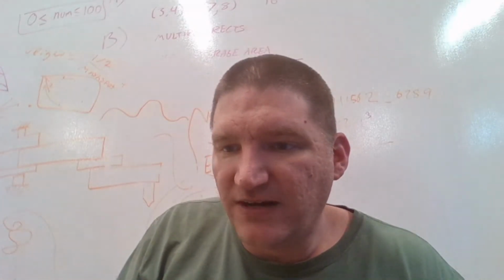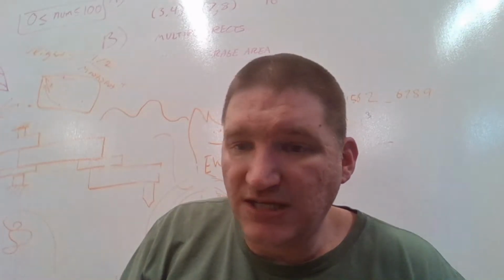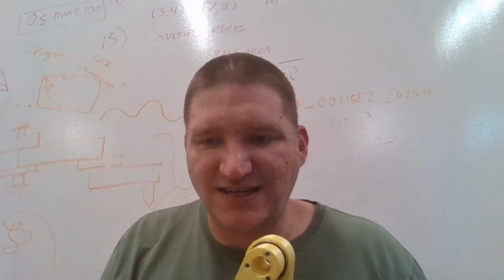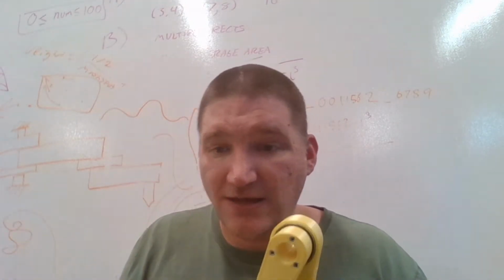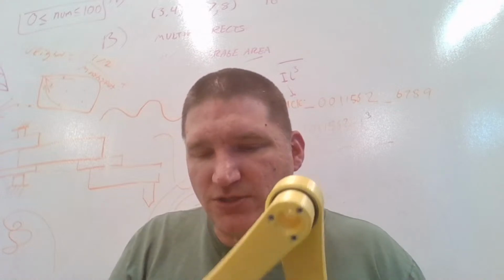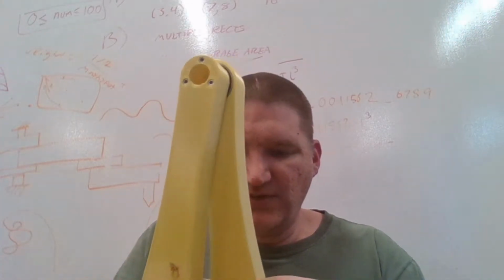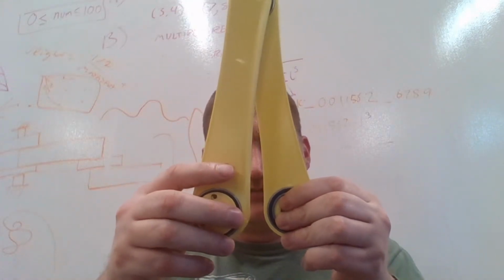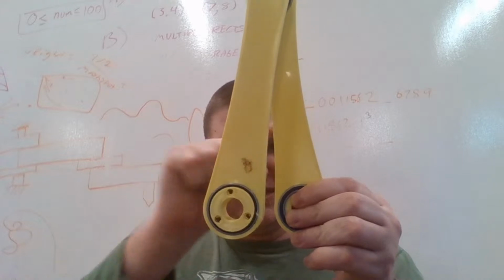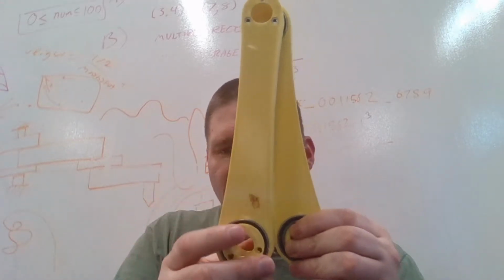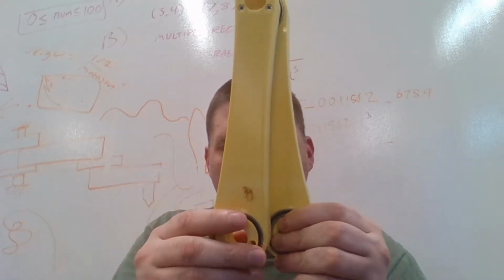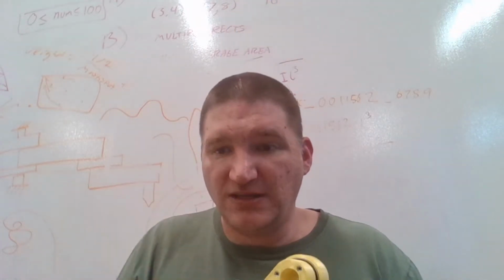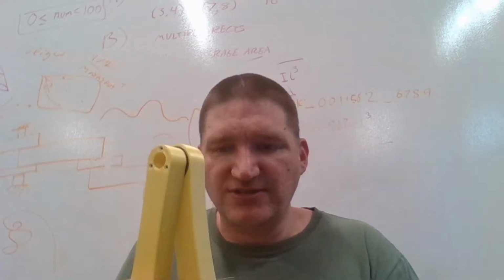Any ideas for varying arm lengths in the same machine? Yeah, in the monorail video, I actually had 2 different arm lengths to keep the elbows from knocking. So yeah, you can do that. The problem is if you have different arm lengths, you can't get close. You exclude a region around the pivot that you can't get to. So if the arm lengths are the same, you can get as close as you want. So the basic idea is to have the same arm lengths. But from one set of arms to the other set of arms, you can have different lengths.